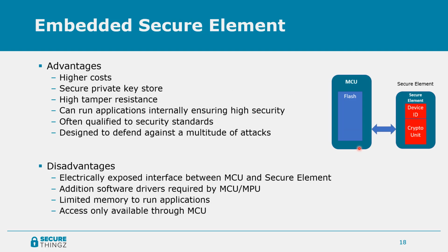Then finally we're looking at an embedded secure element. So the advantages of these are that they have a secure private key store, high tamper resistance, they can run applications internally ensuring very high security, often qualified to security standards, and designed to defend against a multitude of attacks. These are very hardened, robust devices.